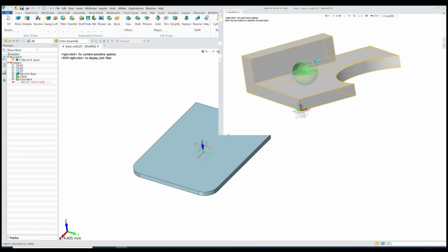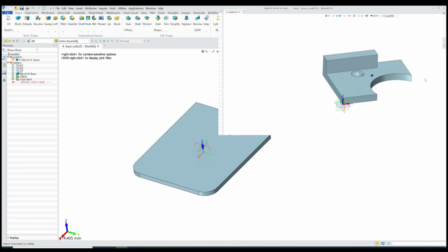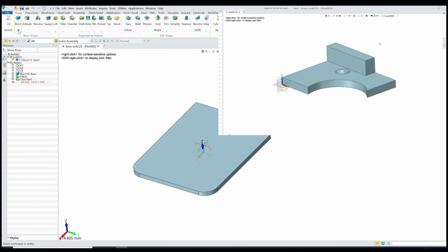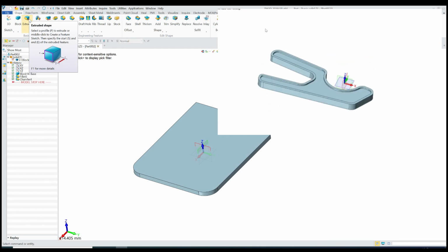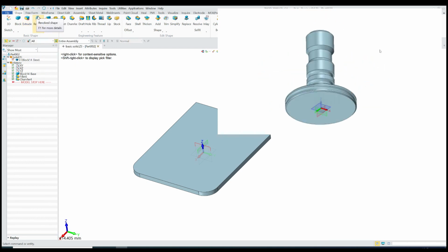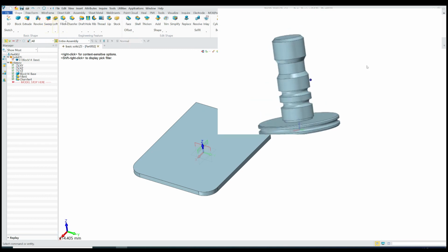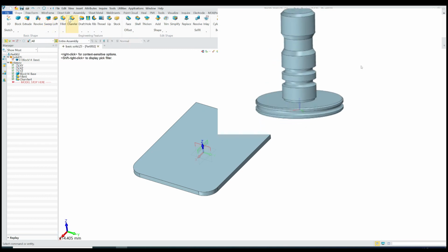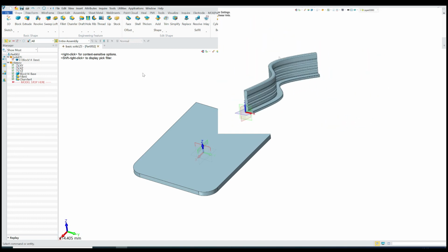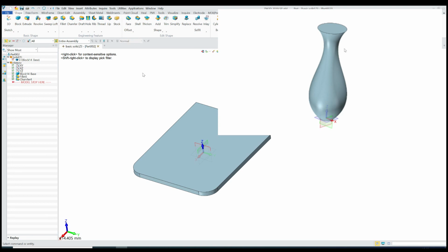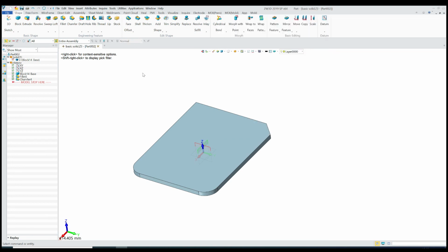For today's lesson, we can recap. We have gone through the basic shapes, how to use them, and the extrude command, how to use it, probably the command we will use most of the time designing. The revolve command, sweep and loft, and we have also looked at the fillet and the chamfer command. And these are commands for solid modeling. Remember that you can use commands in ZW3D for solid modeling and surface modeling. In this episode, we just wanted to focus on solid modeling. We will go through surface modeling in the future, and that is when you create the really advanced geometry.